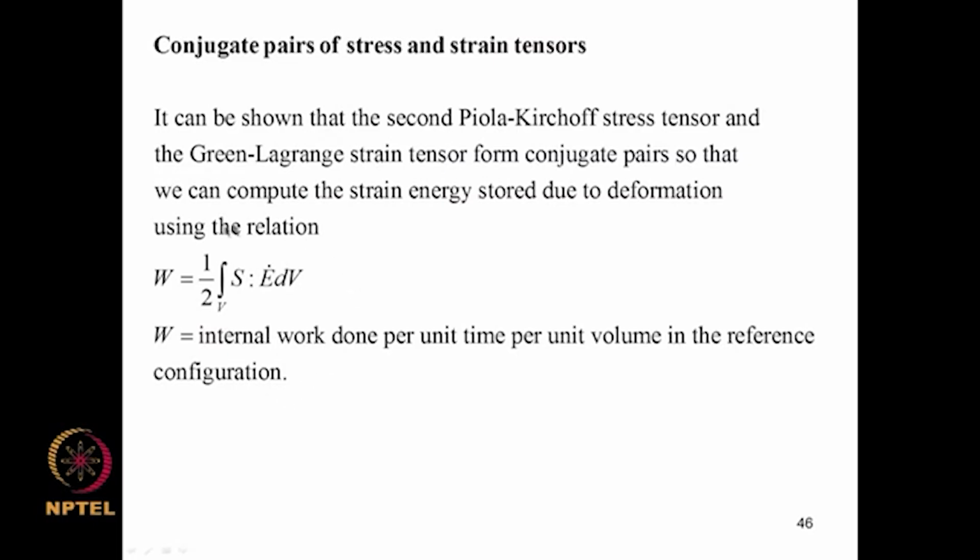So, we start with an expression such as this and use either principle of virtual work or variational approaches, and we will be able to express S and E in terms of the displacement fields, and those displacement fields will be interpolated within an element, and we derive the governing structural matrices and vectors. So, that we need to do.